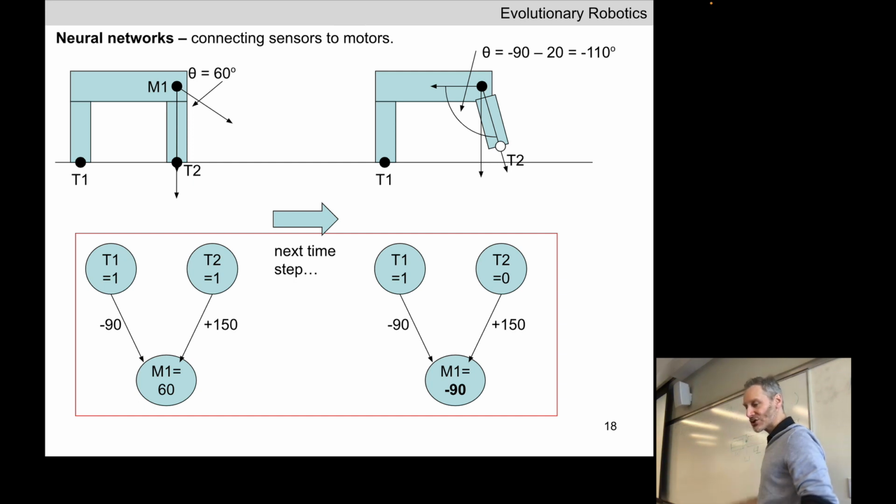Let's say I wanted these 2 parts to rotate like this relative to one another, to twist about their respective long axes. What would be the joint normal that would cause that to happen? Something pointing along the y-axis. So let's define the joint normal to be x equals 0, y equals 1, z equals 0, which as you mentioned would be a joint normal that's pointing along the y-axis.